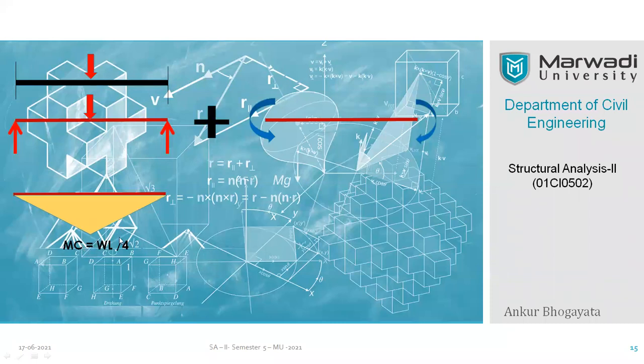So the maximum ordinate, you know from the earlier analysis, is WL by 4. This is a standard formula. So C is nothing but the point at the location of the force. So you have this diagram with you, and in this case, this is, let us say, diagram A. This will be diagram B. The red line is just a beam, the rectangle is this, right? So the value of this moment is nothing but a unit value. It may be MA, it may be MB, both are the same, right? With the same amount of moment at each end, right? Constant moment, we can say constant moment.